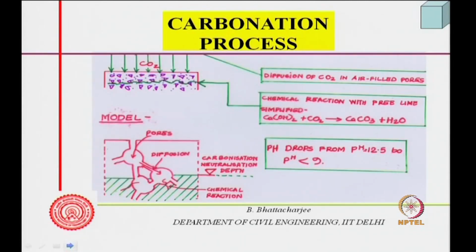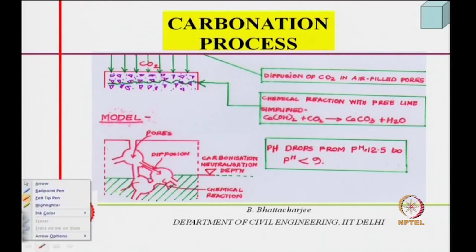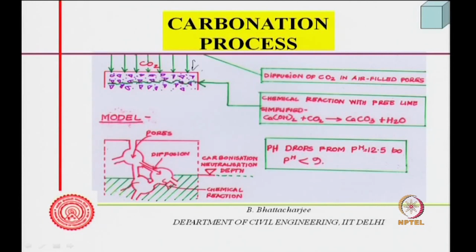Carbonation process, if I look at it: carbon dioxide from the atmosphere penetrates into concrete from the surface as shown here, and in presence of moisture, carbon dioxide plus water can form carbonic acid, and this carbonic acid can react with, let us say, sodium hydroxide to form sodium carbonate plus water.